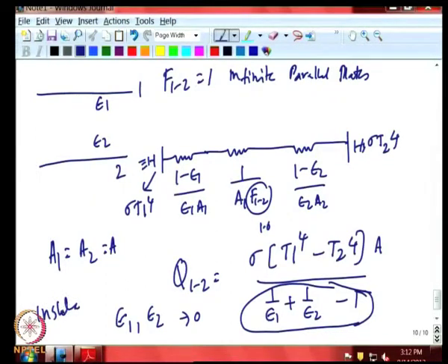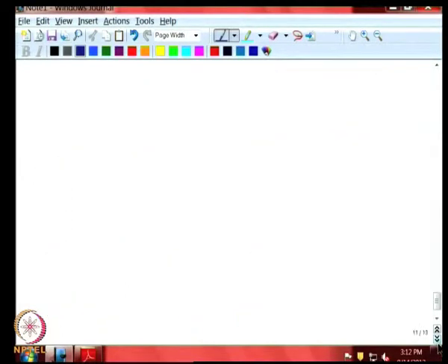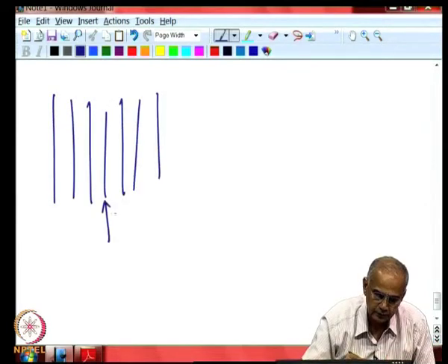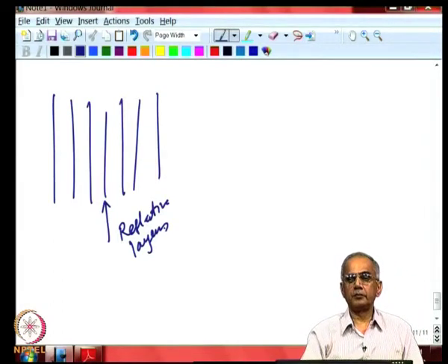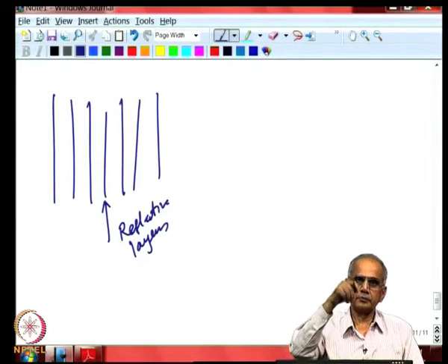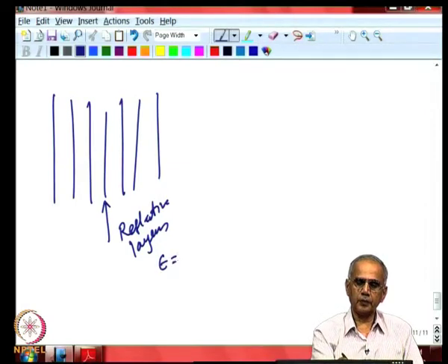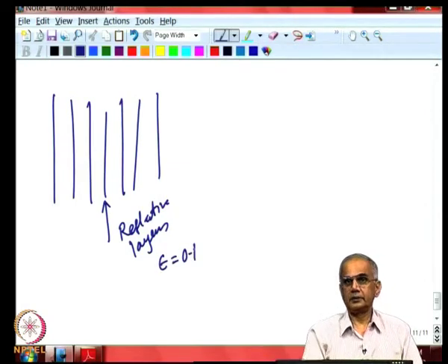This is used in practice in insulation application. So, if you want to insulate a particular object, you take a large number of reflective surfaces and you line them up. So, you have a large number of reflective layers. These are nothing but thin plastic sheets coated with aluminum, and so the emissivity tends to be typically of the order of 0.1 or less.